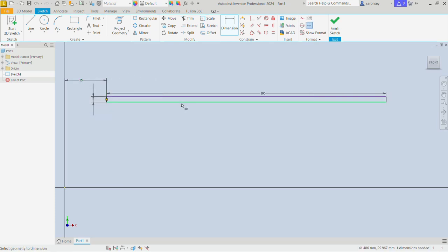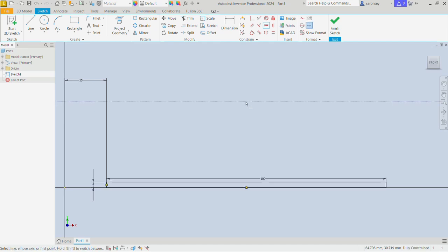And then also we want to align this horizontal line with this point. And so for that, we can use the horizontal constraint command. We click on that. Let's select this point first and then also the midpoint of this line. You look for it just by eyeballing where you think the midpoint is going to be. So there it is here. You know you are there when it turns green. Just click. Now you can right click and then OK.